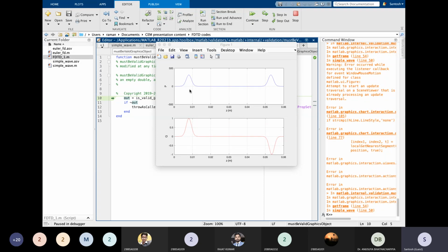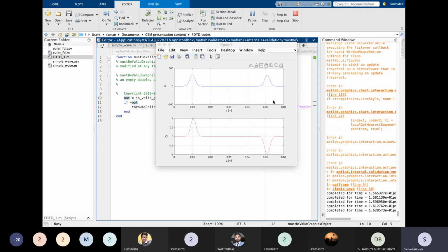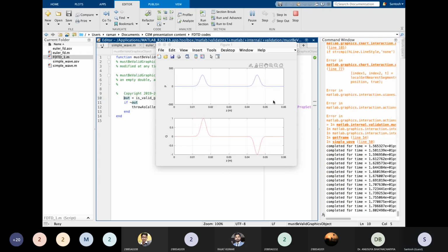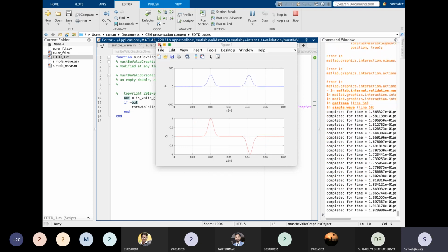So in this case, we have actually not defined the boundary in any manner. We have just updated the equations and you see the wave going. At that boundary, it becomes kind of undefined because you are not told what kind of boundary it is, so it just behaves arbitrarily. So the solution is valid from 0 to 0.06, but at those two boundary points, it's not valid. And after it returns from the boundary, again, it's not valid for those times because you have not actually told what kind of boundary it is. Correct. So this is one thing.